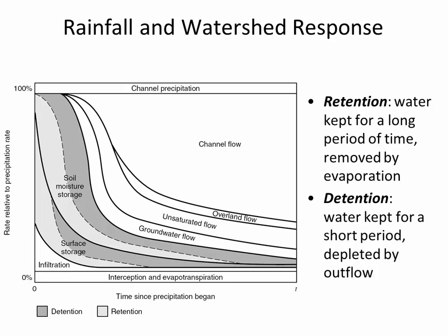Water will be moving through the soil moisture. So in the zone of aeration, the moisture is going to increase. Although it's not going to become fully saturated yet, it takes a little bit more time before the water gets down into the saturated zone and there can be groundwater flow.